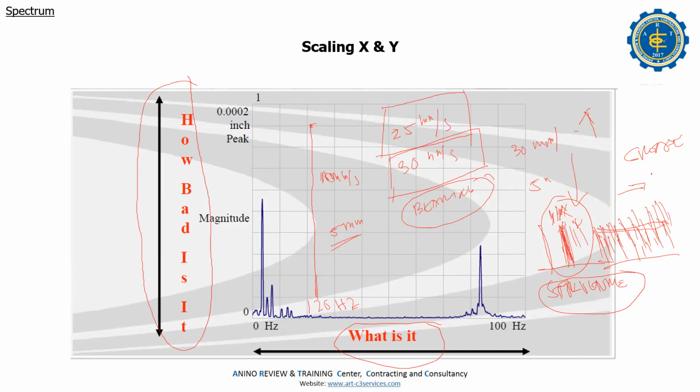You can detect the unbalance, right? But sometimes I get confused with rotating looseness also. If you have looseness, you can see in the spectrum, there's another pattern with mechanical looseness. There is 1x, 2x, 3x. If only 1x, you only have to monitor whether there's an unbalance, but you have to prove that it is unbalance. It is not easy.